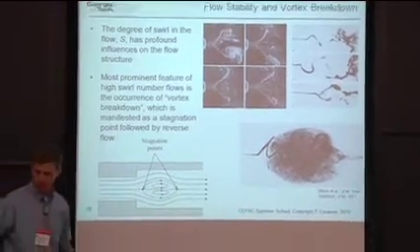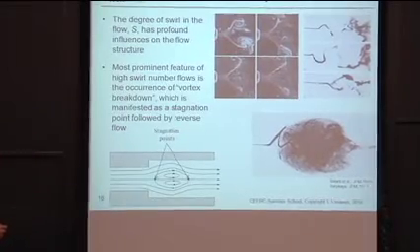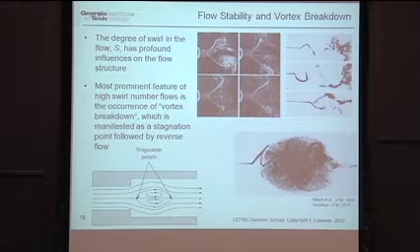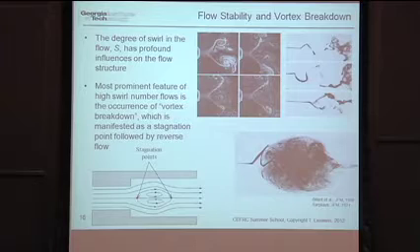And here's a couple nice little flow visualizations illustrating this. This is flow coming out of a jet, and if you use your imagination, you'll see this jet flow coming out, and then you'll see the flow just naturally dividing around something. And you might ask, well, why is it dividing around this? This is the forward stagnation point of the vortex breakdown bubble. So you have this recirculating flow. The flow looks kind of crazy on an instantaneous basis because you have all these hydrodynamic instabilities present. You can see this jet actually gets wrapped around here due to these. You get these helical modes present in the flow.